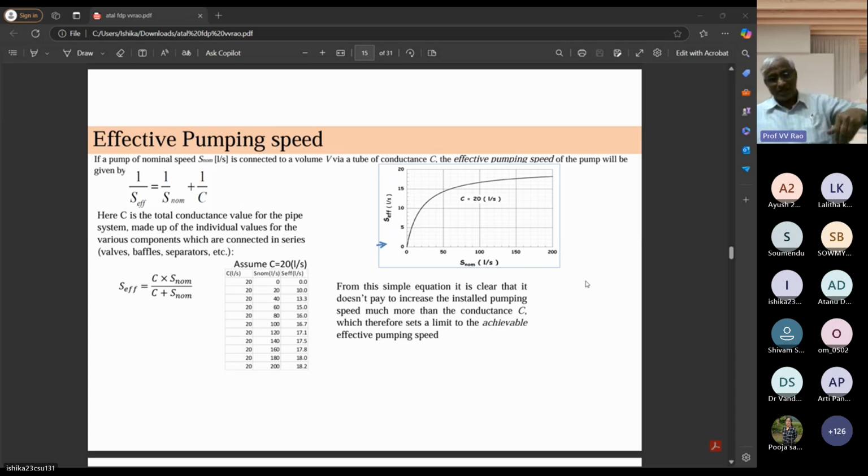There may be gases coming in, intentional gases like argon for sputtering. There may be unintentional, not good gases like leaks, etc. There may be useless degassing, which is giving vapors which are not good. But there may be intentional gases which need to be pumped. Otherwise, if it is flooding, doping will be very high. So doping profiles also need a little bit of control, by not making all the impurities available to the site.